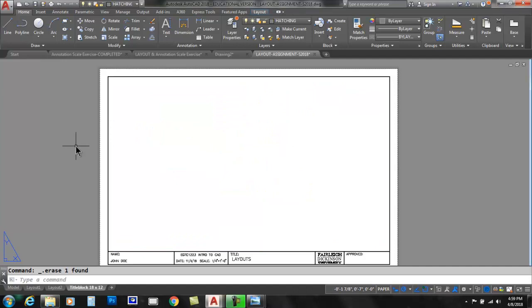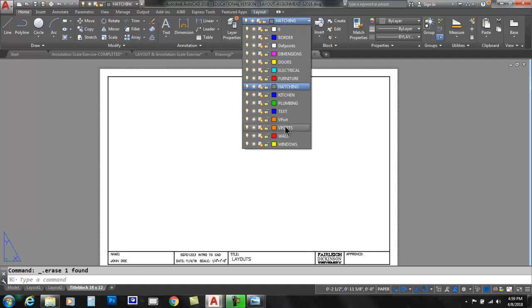Okay? Remember how we started our other drawing. We start with layer viewport. Look what I did for you. I gave you 2 layers. You already have viewports and viewport. So you have to make one no plot and one plot. So if you look at your handout, the main viewport is the floor plan. That one we don't want to plot.